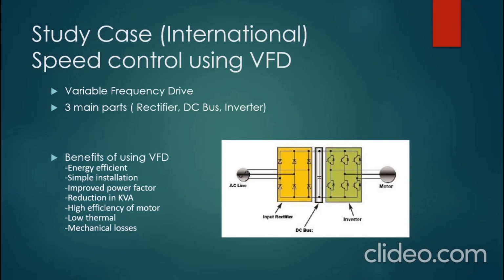The reason why IGBT is used is because of its high current and voltage rating, and very fast switching speed. The IGBTs are connected in H-type configuration, while two PWMs are supplied to it. The first PWM is the normal one, and the second one is the complement PWM. The reason behind this is to excite the first and the fourth IGBT in order to create a rising clockwise waveform, while the complement PWM creates a rising anti-clockwise waveform.